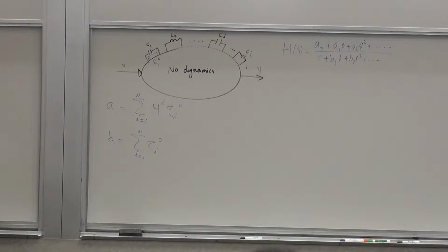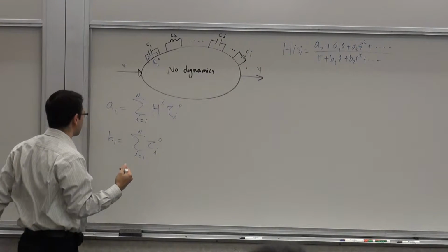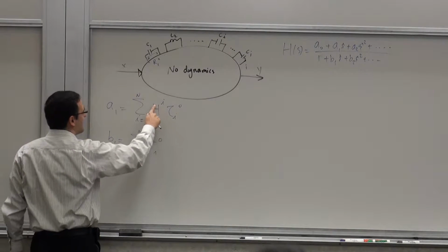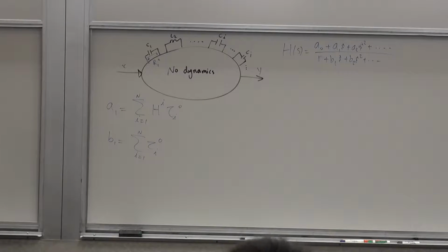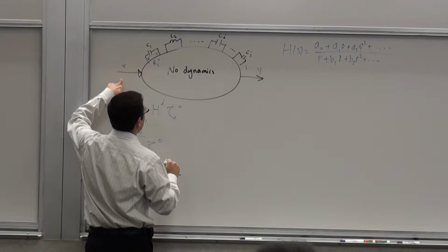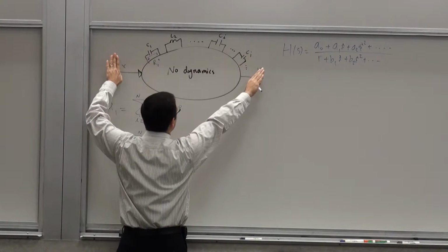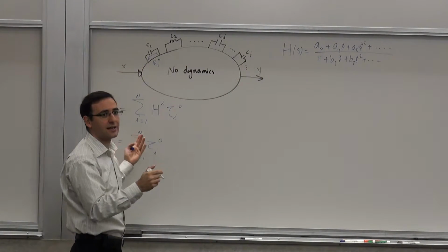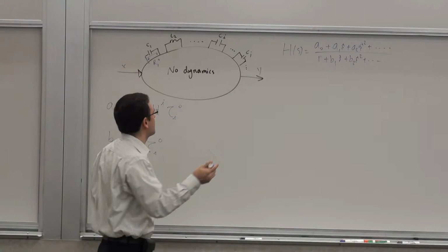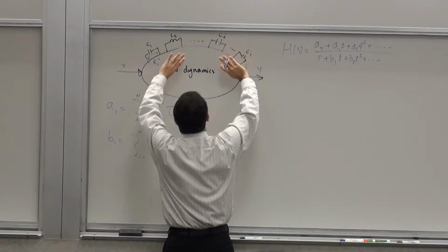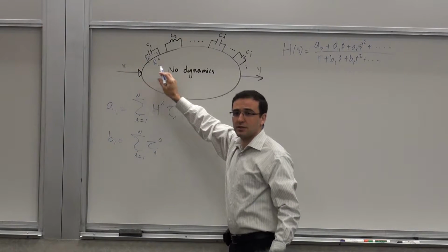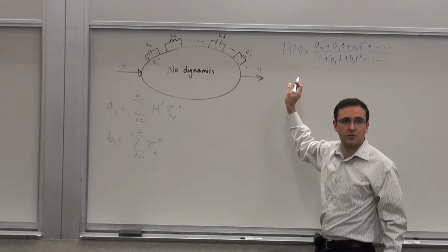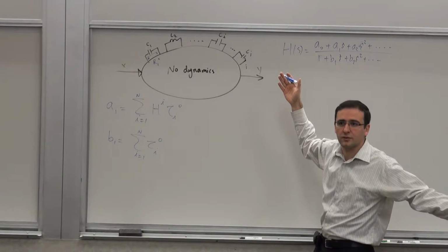All of these R value calculations are low frequency calculations because there are no energy storing elements when you're looking at each one of these cases. So these are the zero value time constants, and you can reuse them. And these are what we call the transfer constants. These are the first order transfer constants, which are basically the ratio of the input to output when all the elements, except for element I, are zero value, and element I is infinite value. So in this case, this is capacitance Ci, this one is shorted, everyone else is zero value. Basically, the capacitors are open and the inductors are shorted, and you look at the low frequency transfer characteristic from the input to the output, which is what we call zero transfer constant, because it's a constant, not a function of frequency at this point.